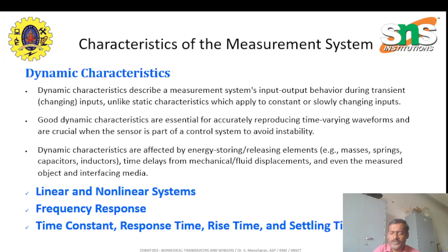So whenever we know a capacitor, whenever there is an instant change in voltage, it won't allow it. Whenever it goes from high to low, the capacitor starts discharging and maintains the previous output. Similarly, whenever changing from low to high, it won't change the output from low to high immediately. Instead, it charges the capacitor, and only after that does it give the full output. So an instant change of voltage is not allowed in a capacitor. Similarly, an instant change of current is not allowed in inductors. So in electronics terms, we can say capacitor and inductor. Similarly, in mechanical terms we can say masses and springs.